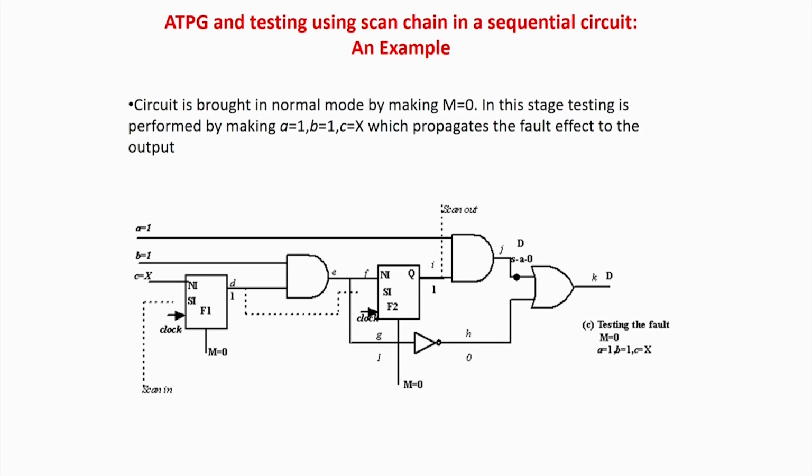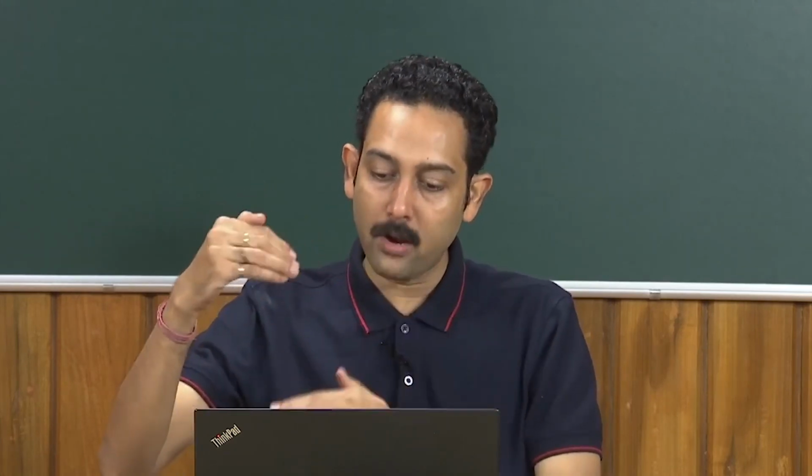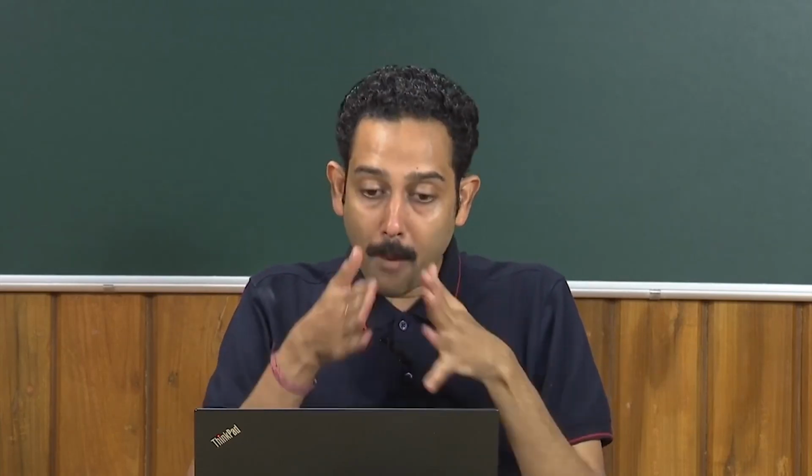So basically what we are going to see is what optimizations can be done in high level synthesis for high level circuits or very complex circuits like NOCs and SOCs. Can I have a very abstract fault model? Can I do the testing at a much higher level of abstraction, at the block level? At the same time, how can I reduce the number of test patterns? Because this RTL or high level test pattern problem is very recent, but before that people tried to optimize how to bring down the number of test patterns with slight compromise. How can I optimize the number of scan chains so that I have minimum extra pinouts, but still can do the scan chains very fast.